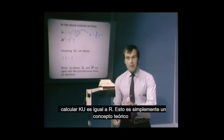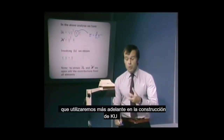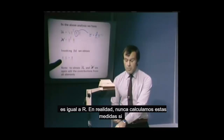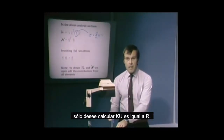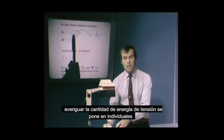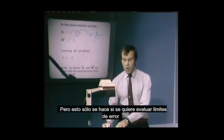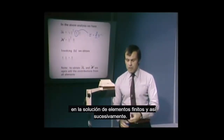This is simply a theoretical concept that I wanted to introduce to you, a theoretical concept that we will be using later on in the construction of KU equals R. We never really calculate these measures if we only want to calculate KU equals R. It might be of interest to us to calculate this in order to find out how much strain energy is put into individual elements in finite element analysis. But this is only done if you want to evaluate error norms on the finite element solution and so on.